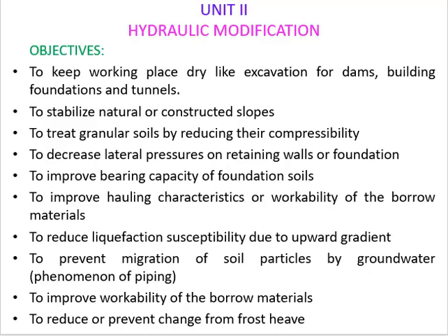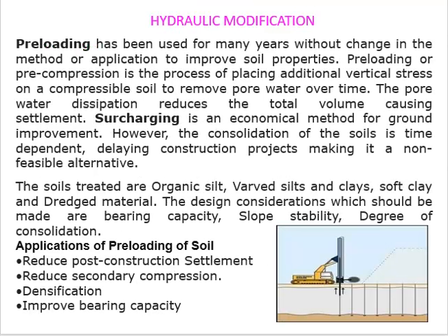There are various hydraulic modification techniques like preloading, vertical drains, sand drains, prefabricated drains, stone columns, vacuum methods, dewatering techniques, etc., out of which preloading technique is the most widely used technique to accelerate the consolidation process of clayey soil.